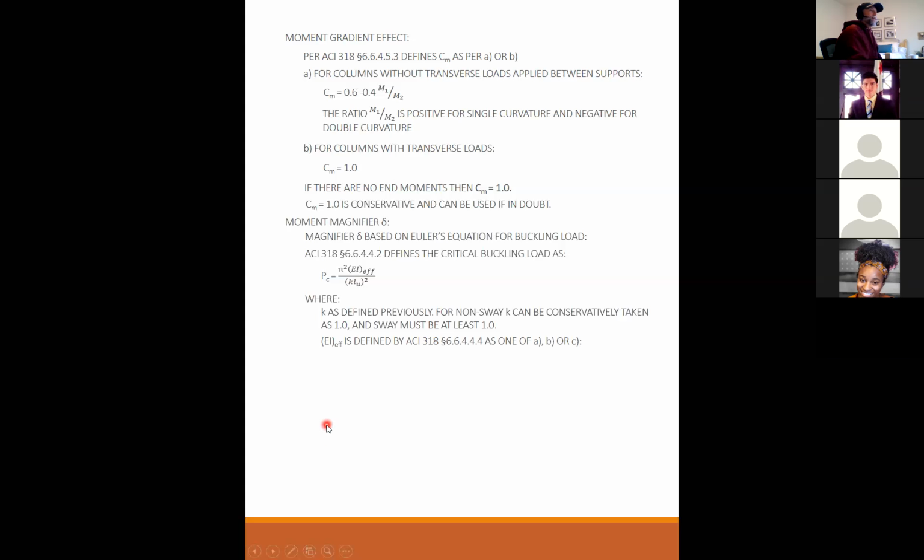EI effective is defined by ACI 318 6.6.4.4.4 as one of A, B, or C. A, EI effective is 0.4 EcIg over 1 plus beta dns, or B, 0.2 EcIg plus Es Ise over 1 plus beta dns, or C, it is the EI over 1 plus beta dns. This is kind of strange, isn't it? Why are we redefining EI effective? And what is this all about?